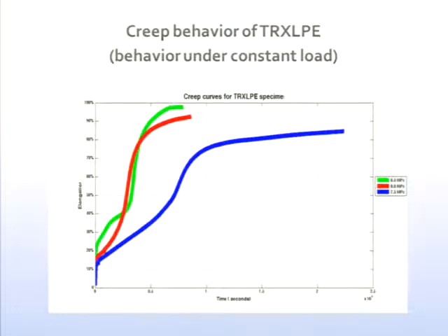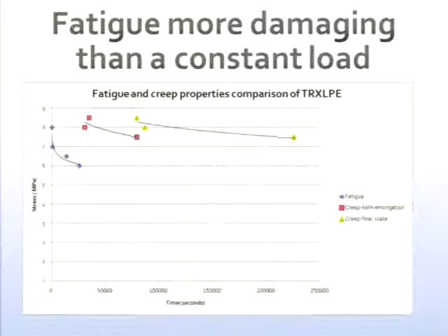So I can take that data and put it on the same plot as the one I showed you a few moments ago, slightly redrawn. So these are failure under creep. Now I've used this as time, rather than using the cycle number, which I used when I plotted that data. But then take this data, since I know the frequency, and I can plot that in time as well. So this is creep failure, just simply the failure of this material when you apply a load. This is fatigue failure. So you can see this fatigue phenomenon is real.